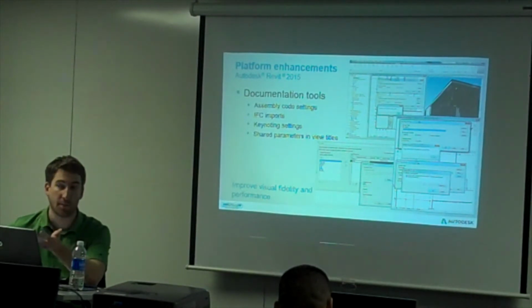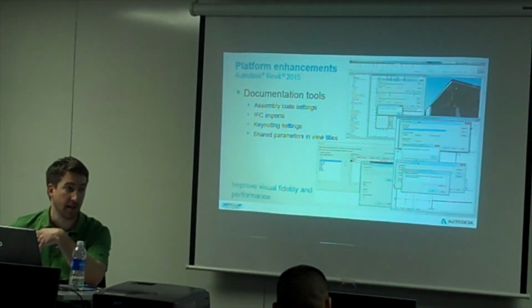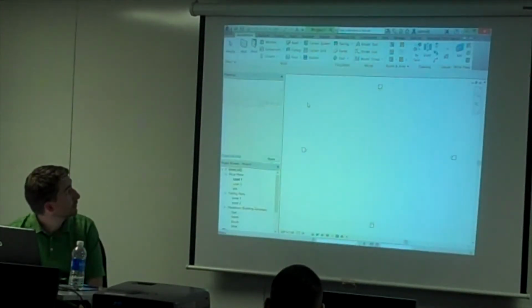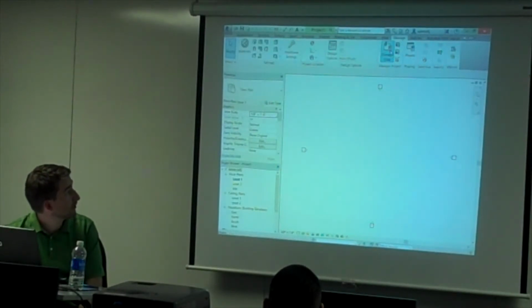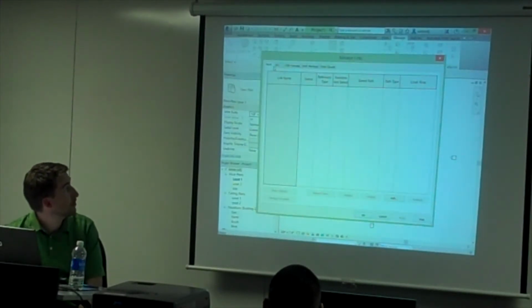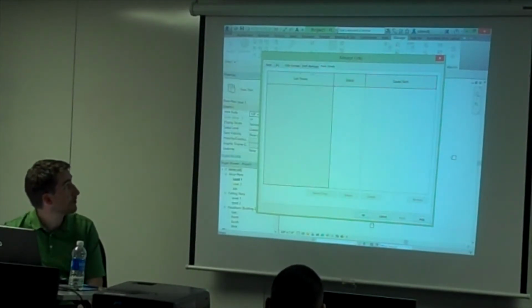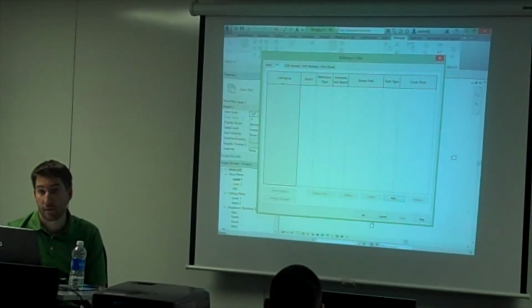But the export, depending on which version of AutoCAD they're running, can sometimes be a very, very large IFC file. It was really bogging down my model. So one of the things you can do with your links, again, you've been linking Revit files or CAD files in for a while, point clouds, but now you can link in somebody's IFC file.